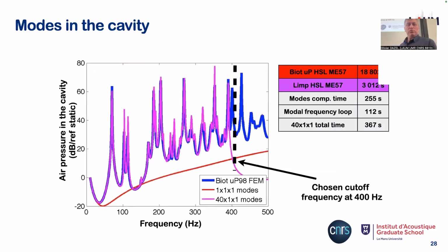If we look to this, and if we want also to, so Romain will present you selection of modes. Here in that result, we were mainly working on the strategy. So we increase mode by mode, okay? And so the first thing to do is to have some modes in the cavity, okay? Yes, because this is the cavity that governs the dynamics, okay? The porous is just having some damping. And you can see that by keeping just few modes in the poroelastic part, one mode in the solid and one mode in the fluid, at least you can have a good approximation of your frequency in the cavity. So which is quite good, but sometimes when doing numerics, we want some very accurate response.